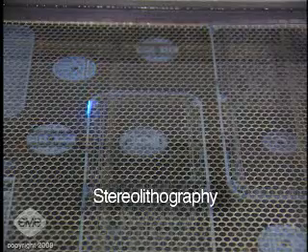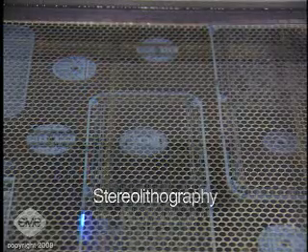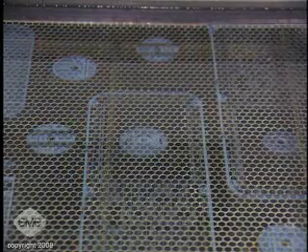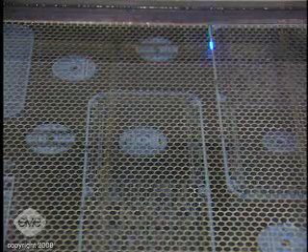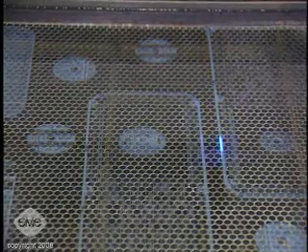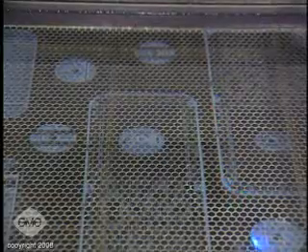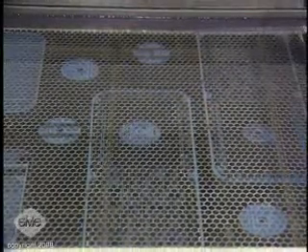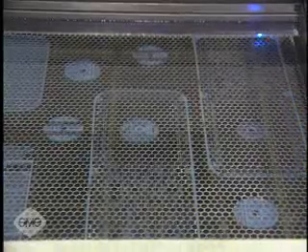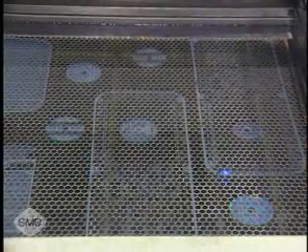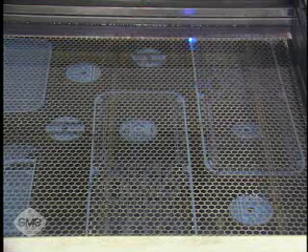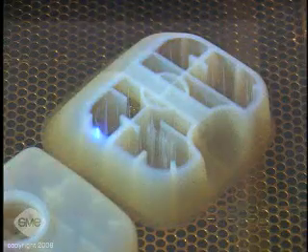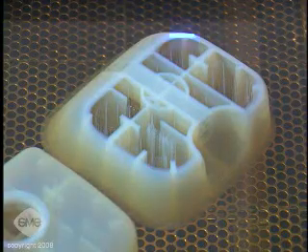Stereolithography, first of the rapid prototyping technologies, is a liquid-based process for making models. The models are built in layers within a reservoir of a liquid, thermosetting epoxy-based photosensitive polymer by selective curing with the ultraviolet light from a focused low-power laser beam. The laser beam continuously traces and selectively hardens the thin layer of polymer according to the CAD file.